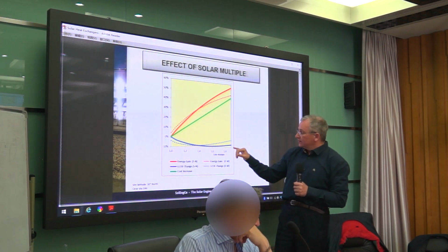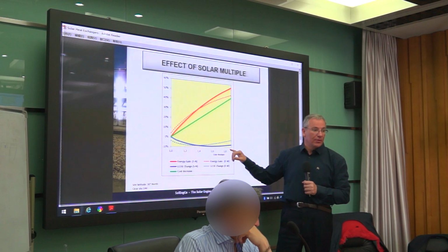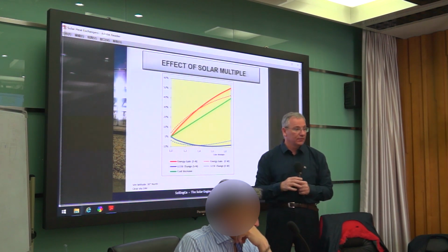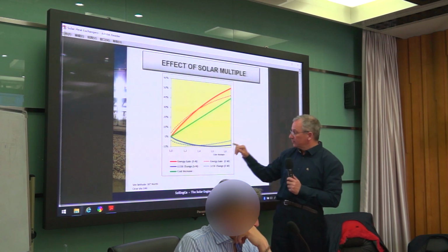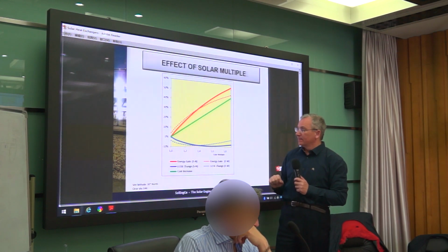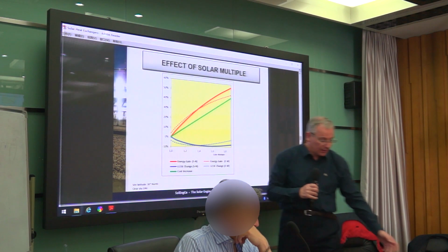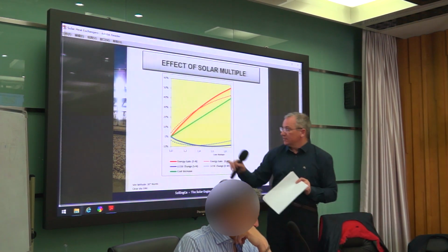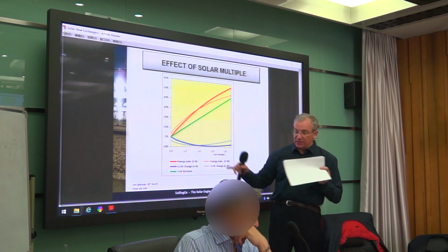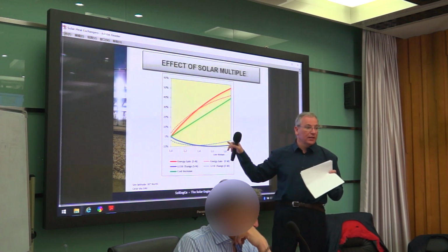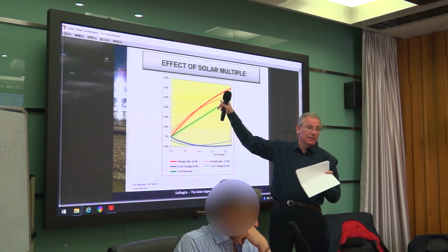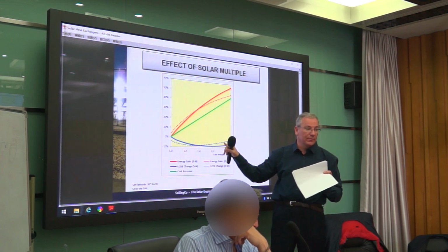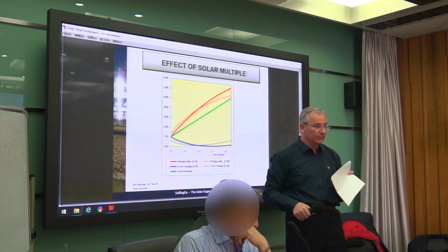But beyond a certain solar multiple it is the opposite, so you go back in this direction. And definitely, if we compare this orientation with this orientation, we see the breakpoint. If we have a disorientation, then the LCOE goes up, because the heat from the solar field is going down. So therefore, this LCOE is going up. Understood?